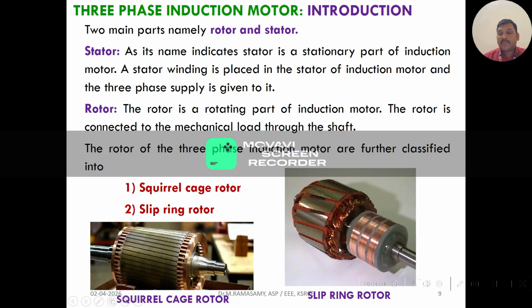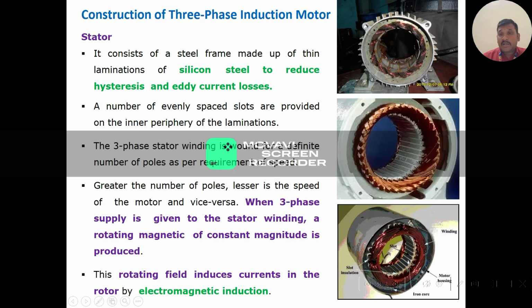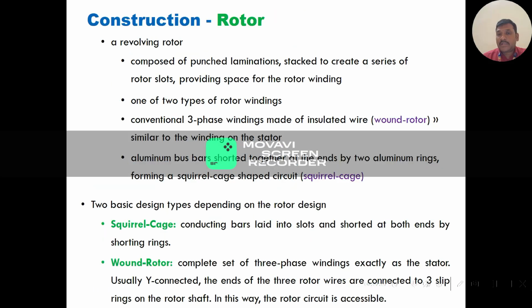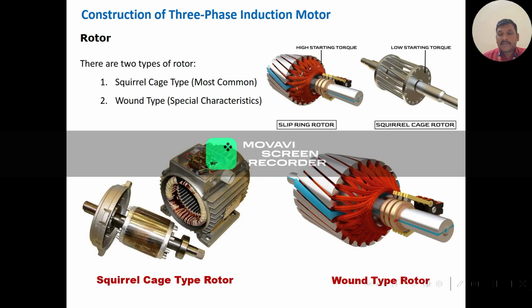And here you see that the slip ring induction motor is made with three-phase windings, which are provided over the slots of the rotor, and they use a skewed type rotor in order to avoid magnetic locking between the stator and rotor, and these three are the slip rings. These are used to connect the external resistance with the rotor circuit. So far I have overviewed the important parts of the induction machine, and here are the images of the stator, which is constructed with yoke and stator slots, and these are the images of the rotor circuits.